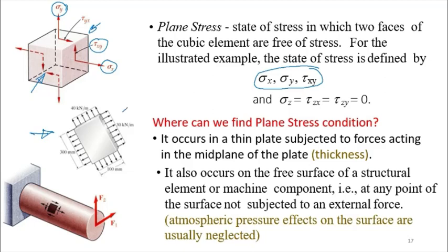So these forces are acting on the mid plane of the thickness of this object here, which is very thin. Therefore, there's very little stress gradient occurring within the thickness itself, and we have 0 stress here and 0 stress on the other surface at the back. And so this is plane stress condition.